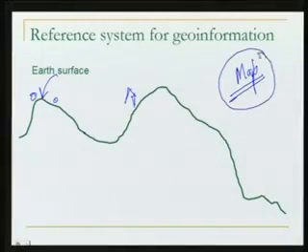Whatever is the geometry there in the ground between different objects, different features, the same geometry is brought here into the lab, and this is the map. So any measurement that we carry out on our map should be same if we measure the distance between those 2 points there on the ground. So basically our map is a geometric representation, in which we are preserving the geometry of the ground and then bringing it in a sheet of paper.